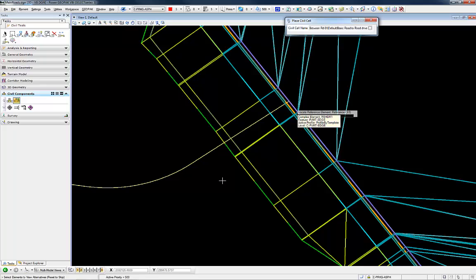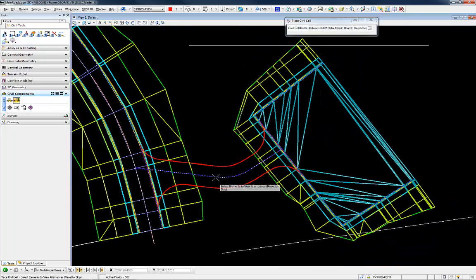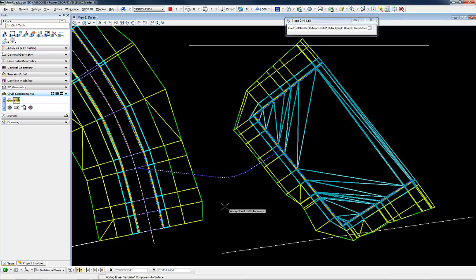Once the cell is positioned, an arrow will delineate along the center line when selected, or touched rather. It's critical that the arrow orients itself the same direction as given in the cell dgnlib. Once we accept it, reading through the prompts, the cell will place.